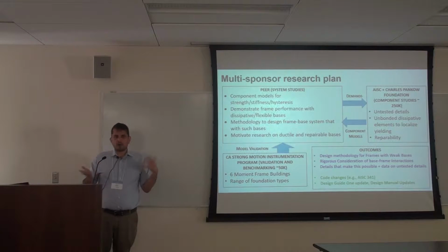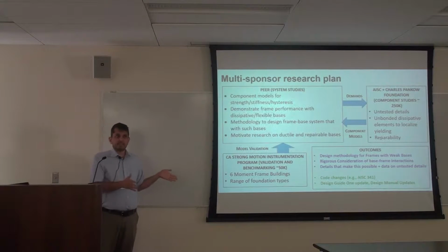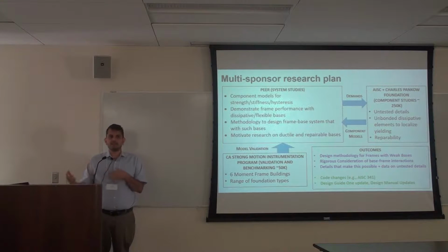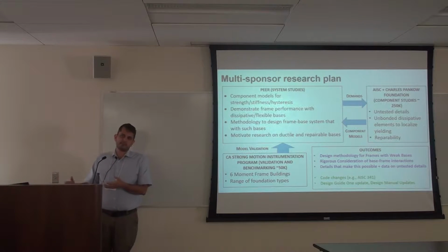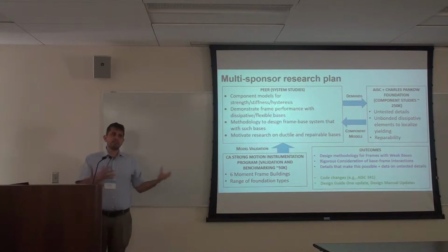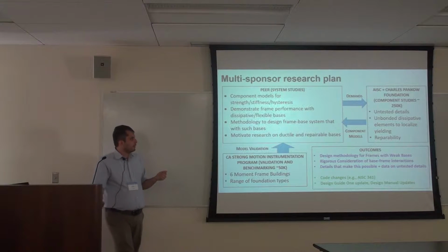So if you think about what all of this entails, it turns out to be a fairly big study, because on the one hand you need to do some physical testing on these connections themselves, just to make sure that you understand their hysteretic response. You calibrate models to reflect that hysteretic response. Then you start putting these models into frame analyses, and then you start running these frame analyses, possibly to get an understanding of the trade-offs between things like the strength of the connection, the deformation demand in the connection, and the performance of the structure.